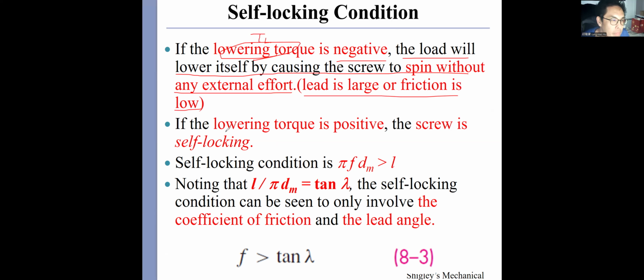If the loading torque TL is positive, greater than 0, the screw is self-locking. That means if I release the nut element, it will stay there.